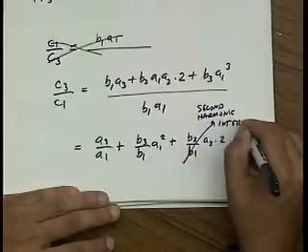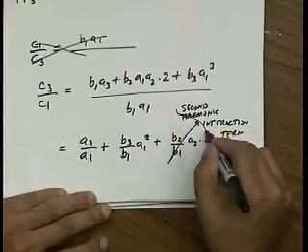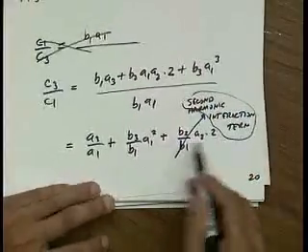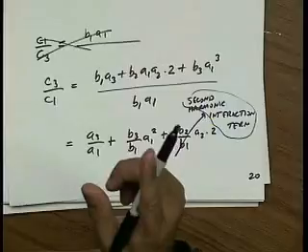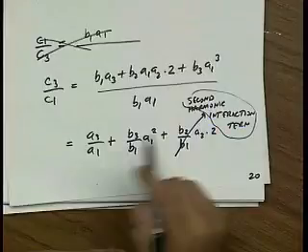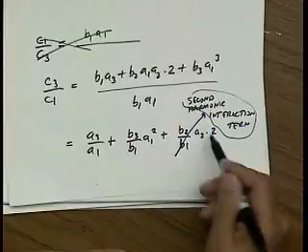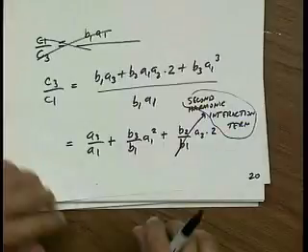We do have a name for it, but we still don't like it. It's basically the second harmonic of the first amplifier mixing with the fundamental, producing intermodulation. It involves an interaction of the amplifiers. It makes things complicated. We don't like complexity, so let's get rid of it.